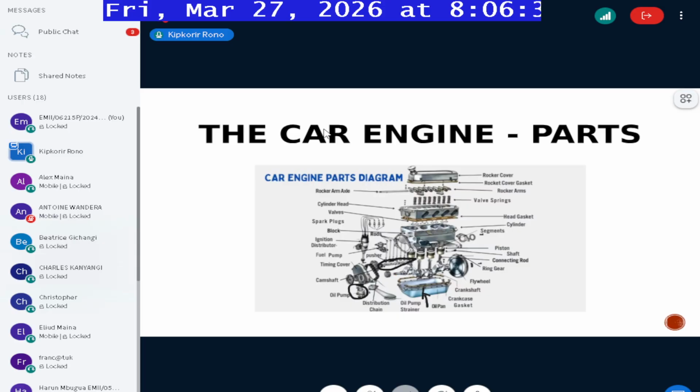Number one is that the temperature in the engine is still very low, and you need the temperature in the engine to build up so that you have a more efficient combustion process. So usually the combustion efficiency at cold start is very low. That's why most of the time when you start the car, you see a lot of smoke at the tailpipe. It's because there's a lot of incomplete combustion going on because the temperature in the engine is still very low. So the temperature has to get to a certain point for the combustion process to become efficient. Okay? Or what you'd call optimum. Not really efficient, but optimum.